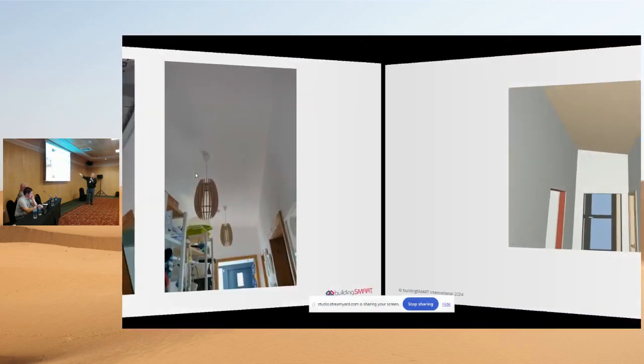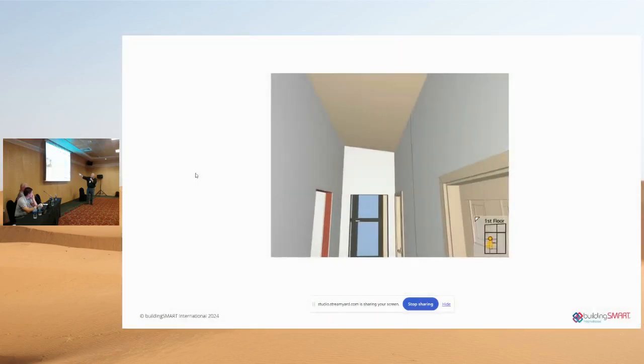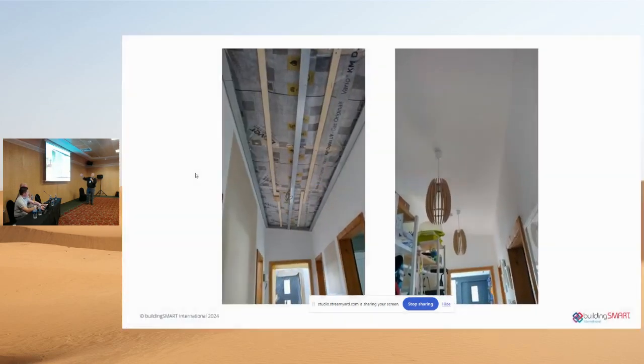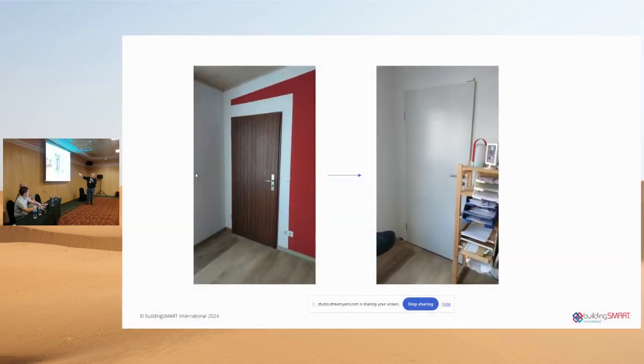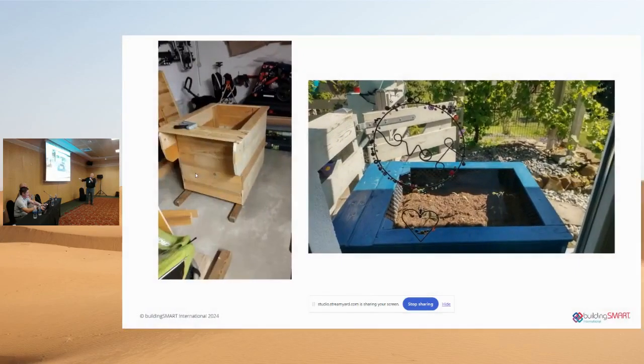Yeah. Oh, sorry, this is the, no. Yeah. This is the architect's rendering of the finished ceiling. So we're going from a darkish board ceiling to a light white gypsum board ceiling. You can see there we've put in all new insulation, clean, mold-free, gypsum wall, painted white, all done. We also replaced the door to the garage, which was an F30 door, with an F90 door that's an insulated metal panel door.